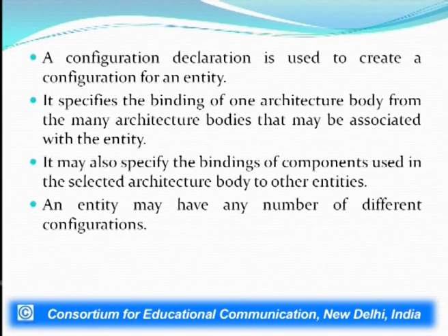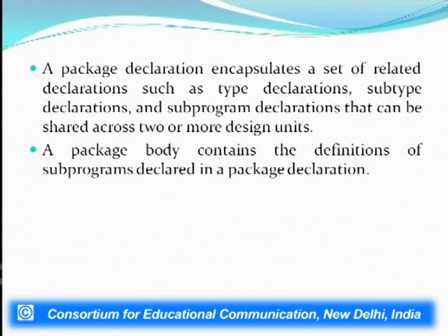The configuration declaration is used to create a configuration for an entity which specifies the binding of one architecture body from the many bodies that can be associated with that particular entity. It can also specify the bindings of components used in the selected architecture body to the other entities. An entity may have a number of different configurations, and based upon the number of specifications of the architectures, that many configurations can be made.